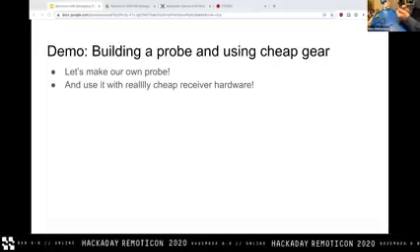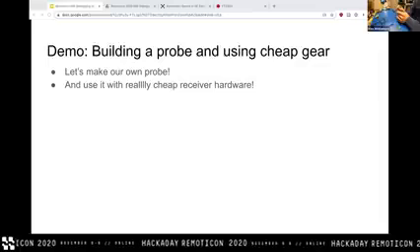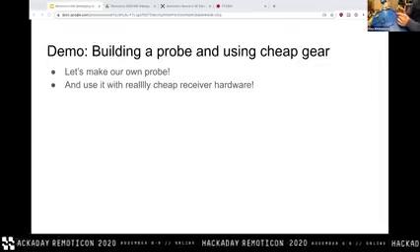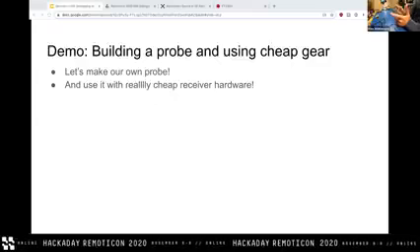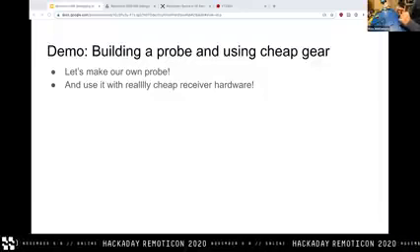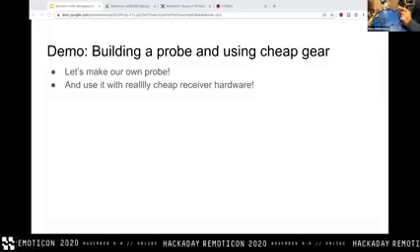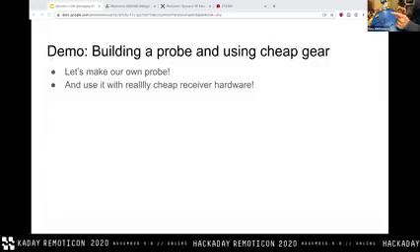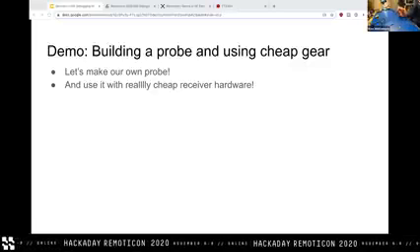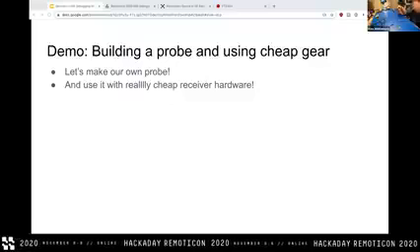So this probe is designed in such a way that there's a magnetic loop up here, and this is sensitive to magnetic field through the probe, through that open loop, but not at all incident electric field, because you're trying to measure just the magnetic field. You don't want this whole thing acting like an electrical antenna and receiving electric field as well. So this probe is designed in such a way that there's a conductive shielding over the entire thing, though split so that there's still a current loop for magnetic field to induce a current and therefore a voltage.